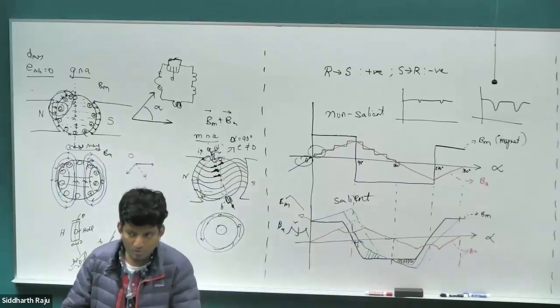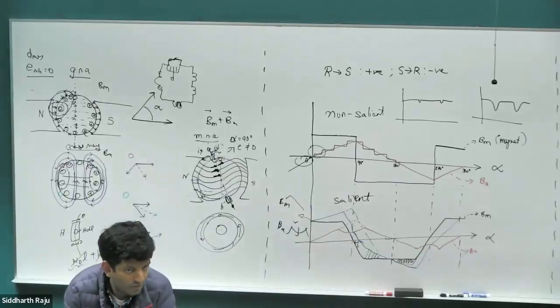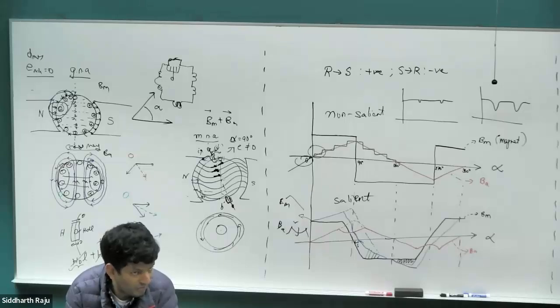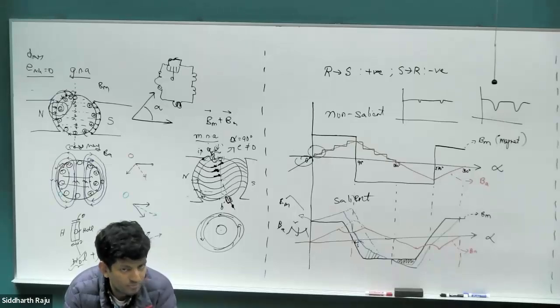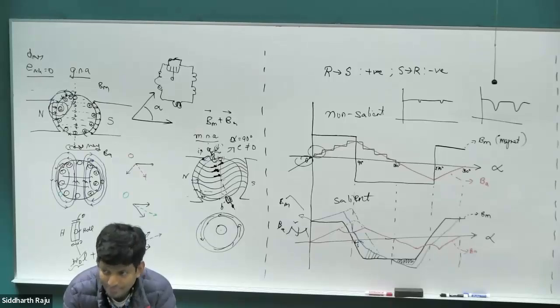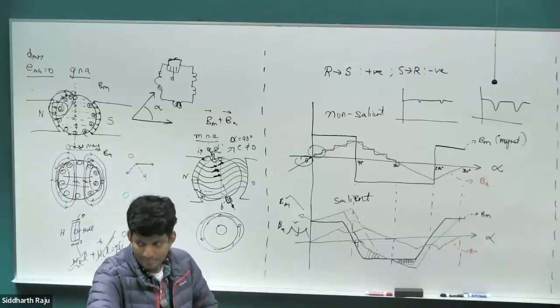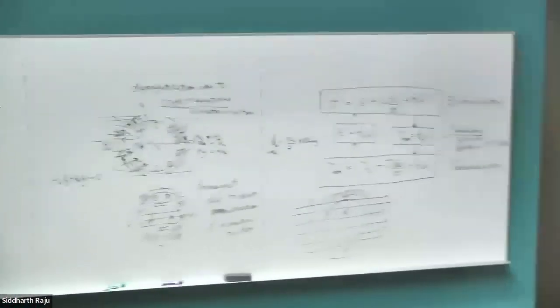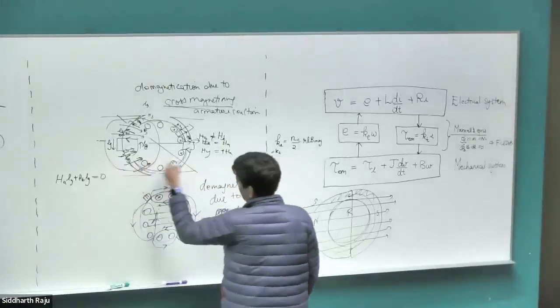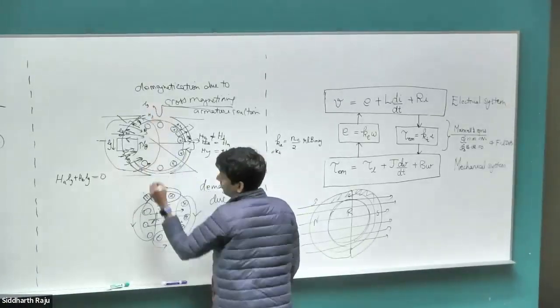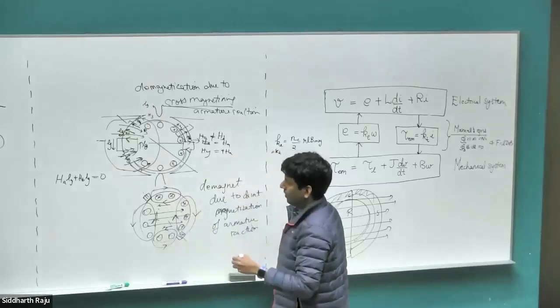So what were the other two methods that we discussed to eliminate armature reaction last class? What were two other solutions? Yep. Was one like placing electromagnets perpendicularly to the stator magnets? Perfect. Remember the name? Right, interpoles. So it's basically a pole placed in between the two other main poles, right?